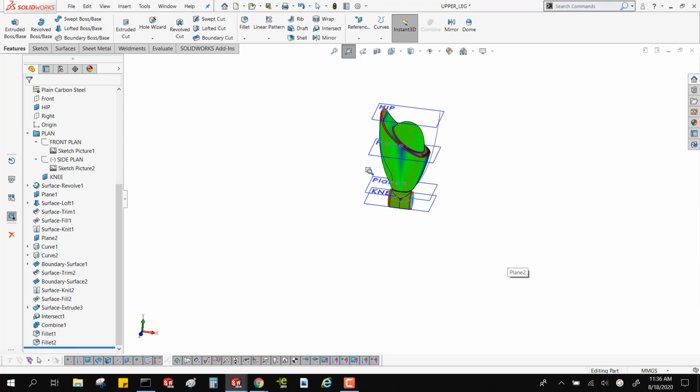Like I said, it's really hard to get a spline fully defined. Even when a spline turns black, it still isn't really black, because you can go into nodes and start messing around with the tangency at different points. When you're dealing with prismatic features, cylinders and plates and things like that, we always want to have it black because we want to tell the guy, hey, this is exactly what we need.